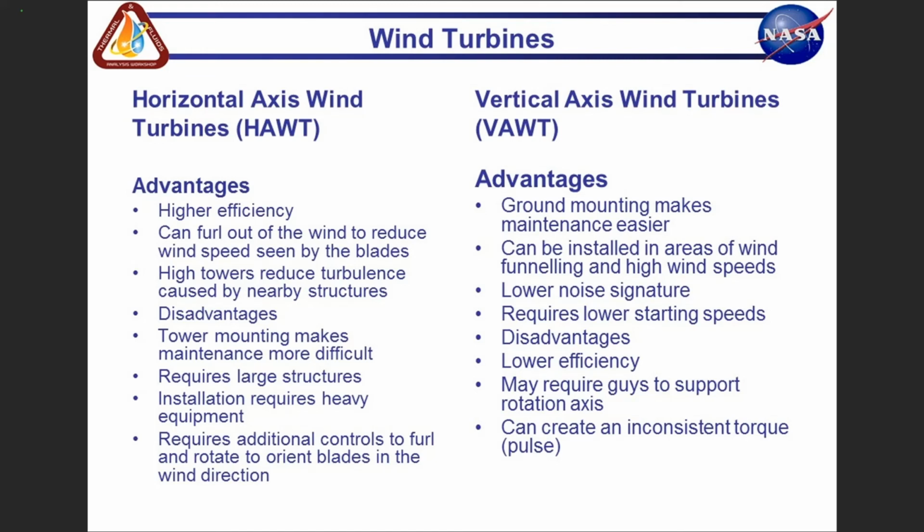As a result of our comparison, the Savonius turbine with 2 blades is more efficient than the Savonius turbine with 3 blades, because when we put 3 blades inside the Savonius turbine, it does not give high efficiency. And the 2-stage Savonius turbine gives the highest efficiency, so we can conclude that it gives more power than the Savonius turbine with 1 stage and 3 blades.